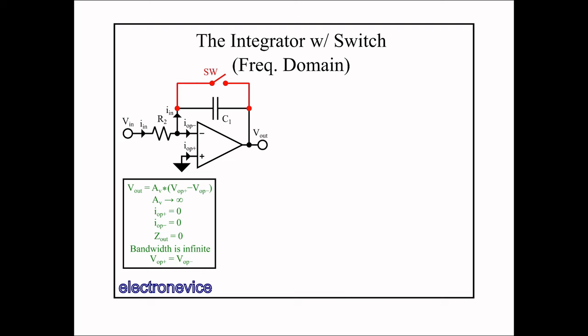Before we move on from the integrator, a practical limit for the integrator gain is still the real op-amp's gain. So even without the resistor in the feedback loop, the integrator will be limited by the maximum open-loop gain of the op-amp, which, while high, is not infinite, so deviation from a pure integral will occur over long stretches of time even with no feedback resistor.